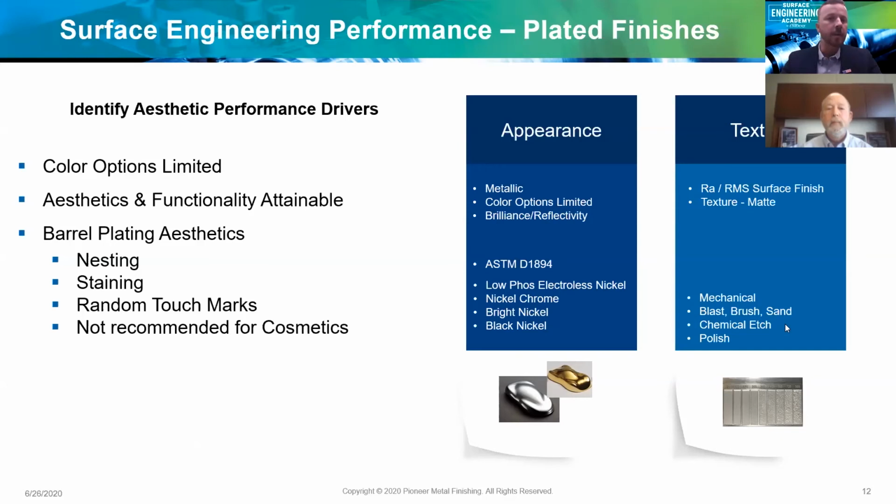And of course, if you have any sort of blind holes or recessed areas where solution's not going to drain out, you're really at the mercy of the barrel plate process, and it's not recommended. A bit of process chemistry splashed over an entire load of parts, you probably lose half the parts in terms of fallout and requiring rework. So again, think barrel plating as really your cost-effective way for functional performance coatings on a select shape or style of part.